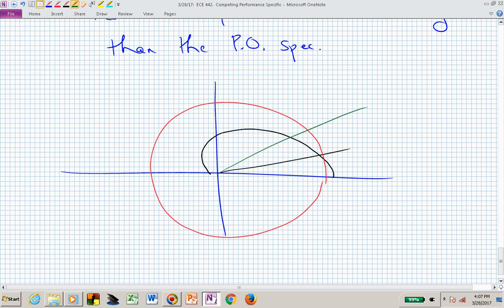If we said we wanted less overshoot and we simply made zeta bigger, then that would mean that we would have a logarithmic spiral that's collapsing towards the real axis. And if we simply looked at that relative to the same radius, if this was our radius before, now there's our radius, we've actually made our angle smaller, and we wanted our angle to be bigger.